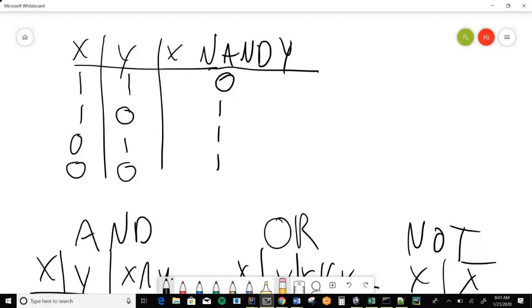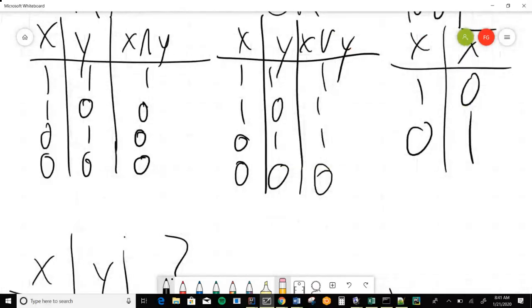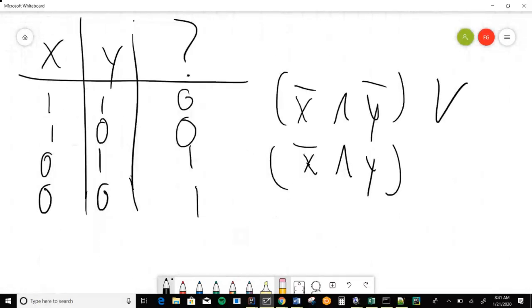Cool. Any questions so far? It's a pretty powerful idea. Literally any truth table you can construct with ands, ors, and nots. Literally any. As in, if you're ever in doubt about how to build one of our logic circuits over the next couple of weeks, if you're just totally lost, what you can always do is write out the truth table and read out of the truth table a circuit with ands, ors, and nots. That is, once you've figured out how to make them from NAND.